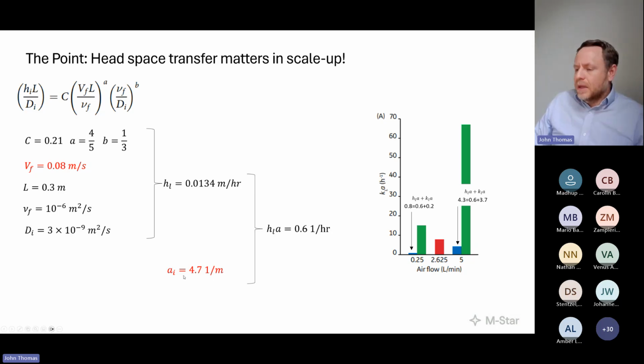And just to be clear, one comment on this slide, just so folks understand where it's coming from. The red values are coming out of the code. We already determined what these parameters should be. That's the vessel diameter. These are physical properties. The code isn't figuring out what the viscosity of the fluid is. These are input parameters. The code is figuring out the velocity of the interface. The code is telling us the specific surface area. And these inputs ultimately derive, via the correlation and via the definition of HLA, what the HLA is.